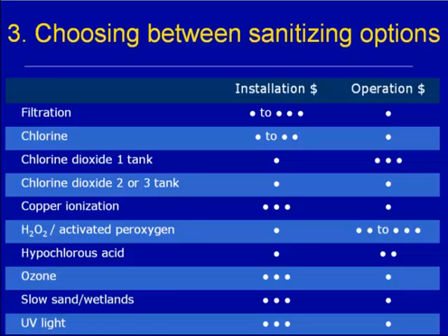So the installation cost could be very low with a simple injector, or for it to be a more effective, more controlled system, there's also pH control of the water and measurement of oxidation reduction potential, ORP, as part of the control system. So that's going to lead to a more safe and effective system and using less active ingredient by having a better control.